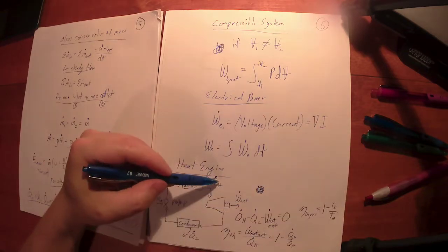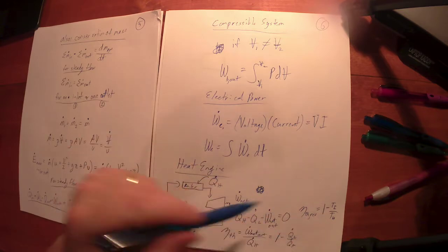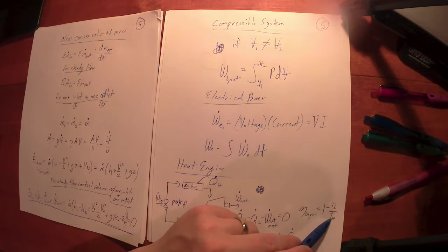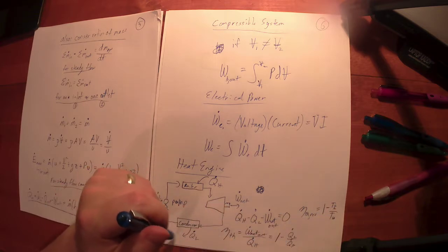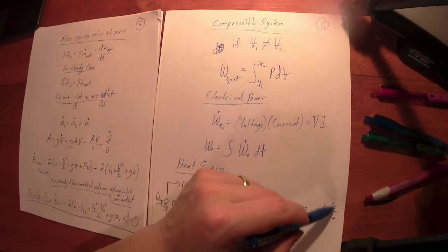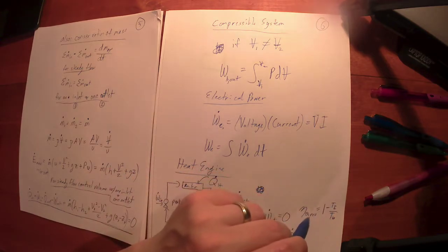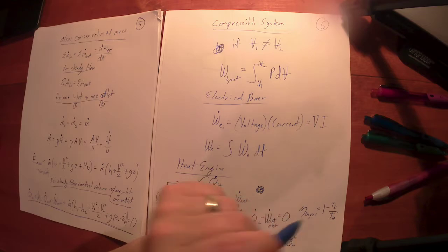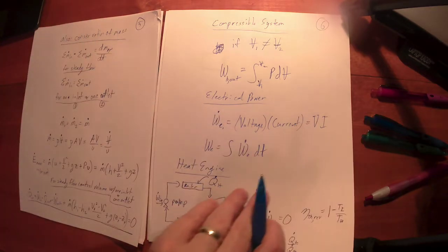The temperature at which this heat is being moved in, so whatever the heat source is, the temperature of that heat source, that's the bottom of the quotient here. On the top of the quotient there is the temperature with which we're rejecting heat to. So the maximum efficiency for this device is determined by those temperatures. Right? And that's based on Carnot principles, and that's true for any reversible heat engine. Okay.